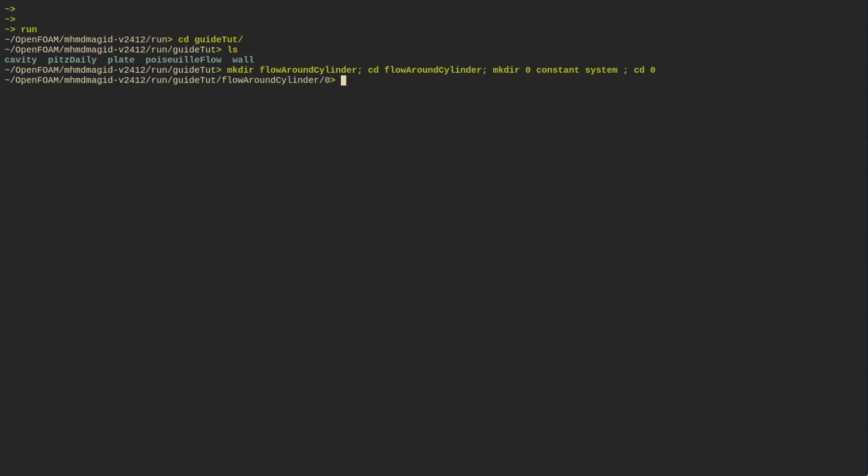And here, unlike other codes that bundle everything together, OpenFOAM requires a separate file for every variable you are solving for. So you will need a file for pressure and another file for velocity. And if your simulation involves turbulence, you will also have input files for parameters like k, epsilon, omega, and so on. Each of these field files is responsible for two critical things: setting the initial values inside your domain and defining your boundary conditions.